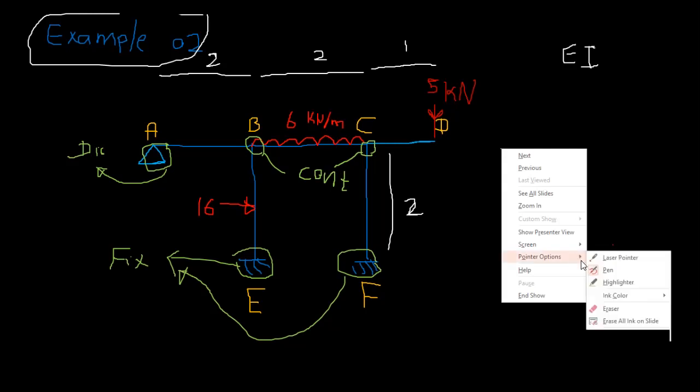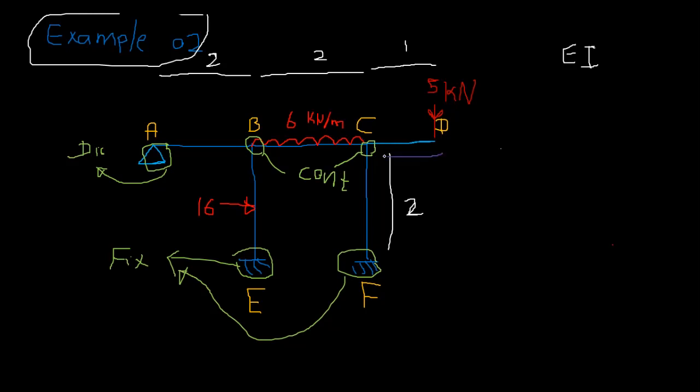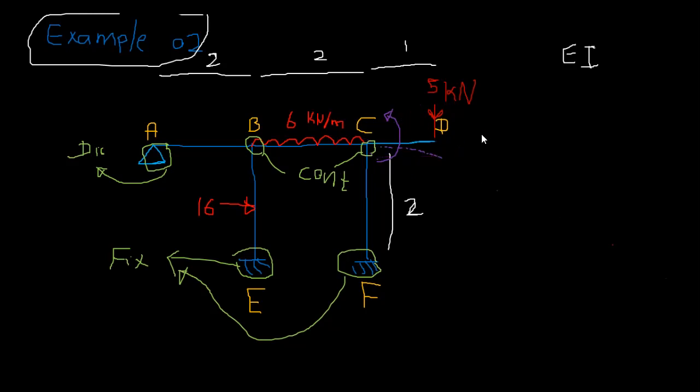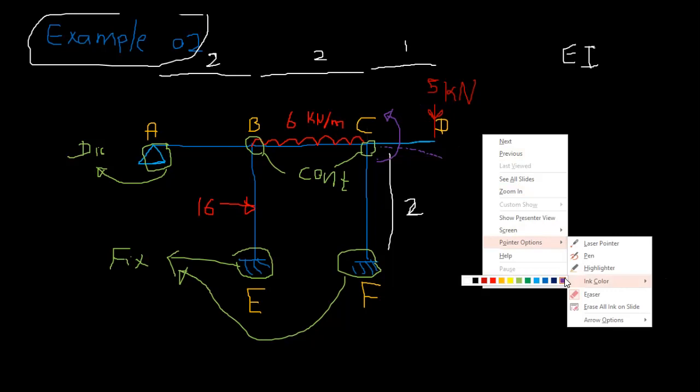This part we need not worry about. Why? It's a cantilever part. It's a special one, so I purposely considered that, because this part is determinate. If you apply such a moment, it is going to be in this shape, so the member will resist it in this way. We already know the final bending moment, so no need to use that part.